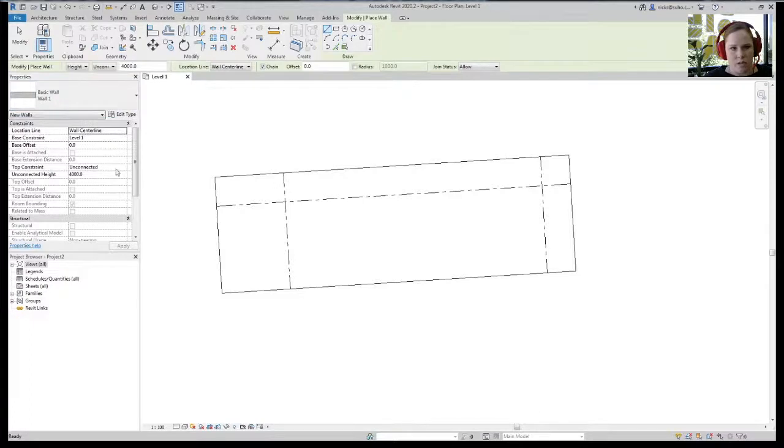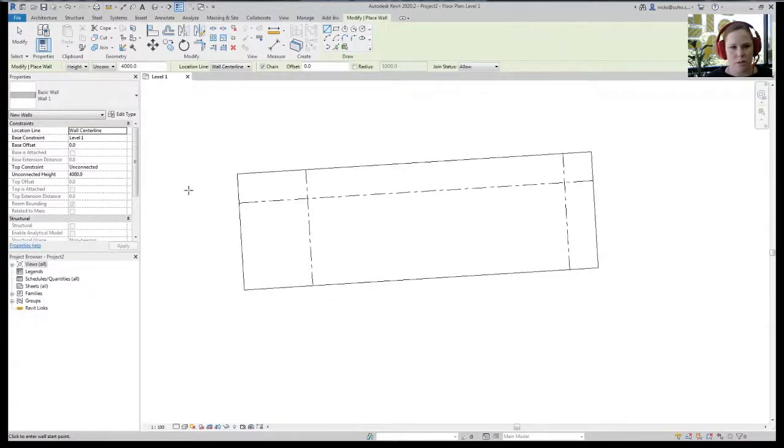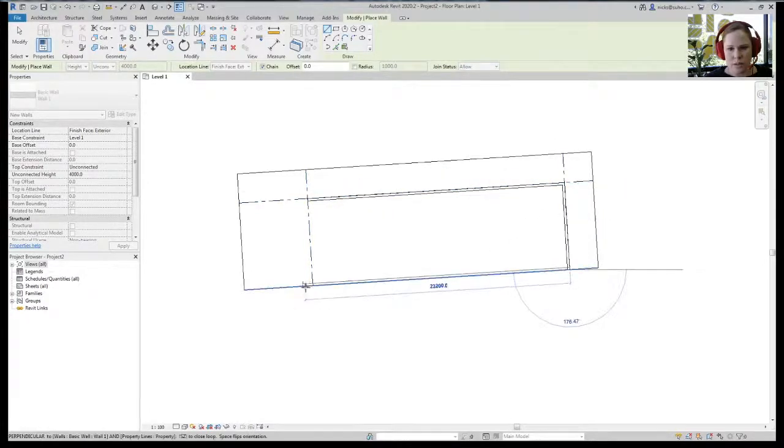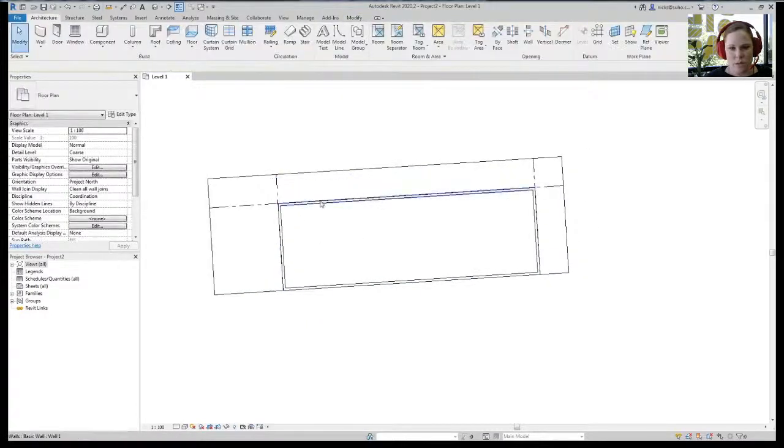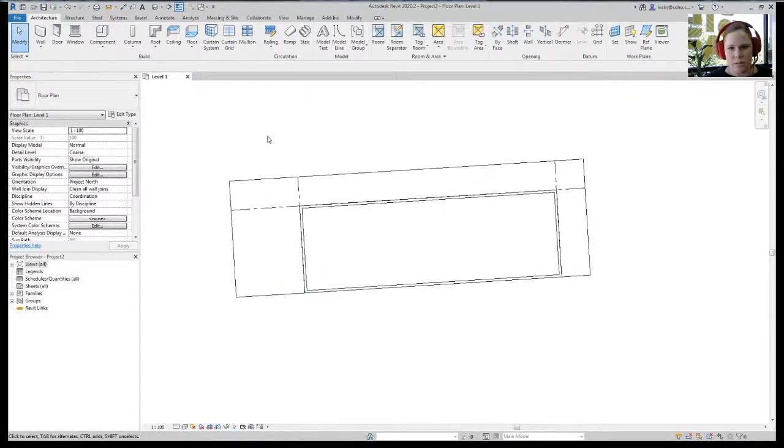Now, a very easy way to calculate the data that you need for Hubble, you can do in Revit, and I'm going to show you. So the reason I'm showing you how to set it up is so that you can actually do it in your own Revit file. Very easy, or you can add these little processes to your workflow as well. So what I'm doing is drawing around this boundary line, which is essentially showing how far the building needs to be set back in this instance.